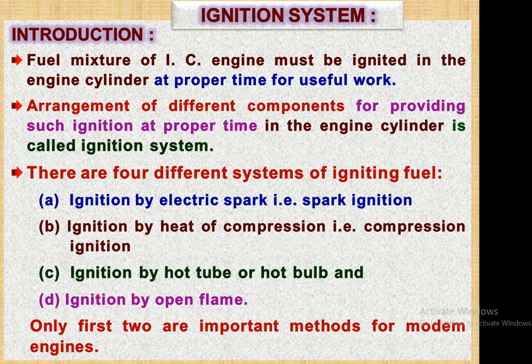So there is no need of a spark plug or any ignition system in the compression ignition type of engine. But in case of a petrol engine, we are introducing an air fuel mixture inside the cylinder, and there is not a very high temperature of the air fuel mixture after compression. So in this spark ignition engine, there is a provision of a spark plug which produces a spark and ignites the air fuel mixture inside our engine system. So we will see the ignition system that may be employed in the spark ignition engine.